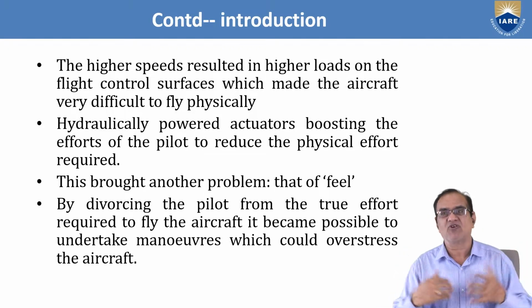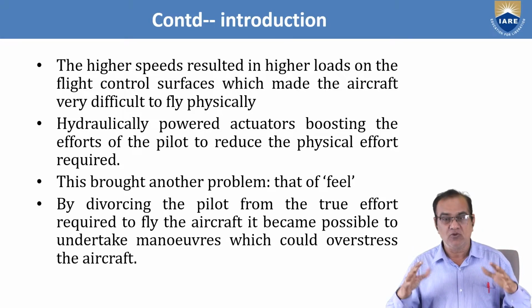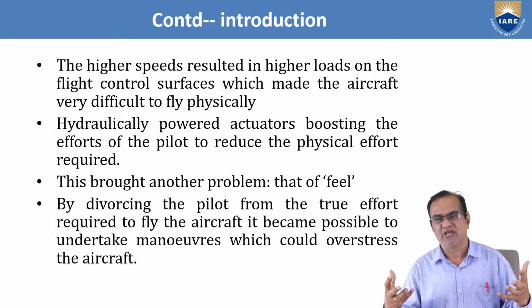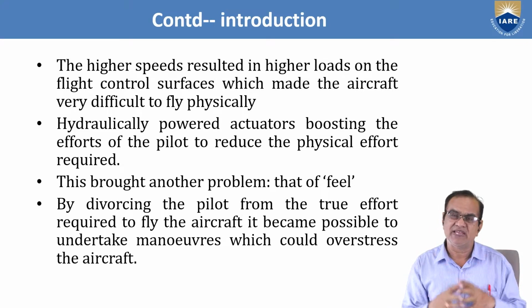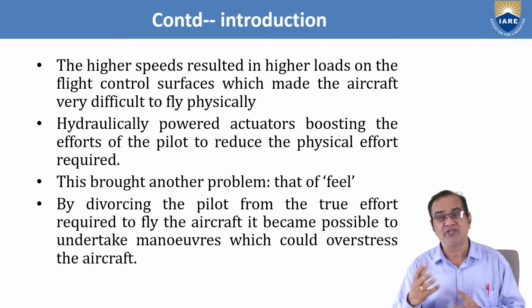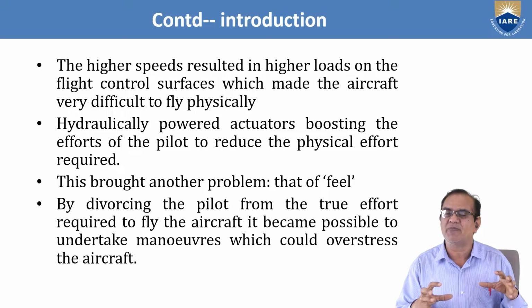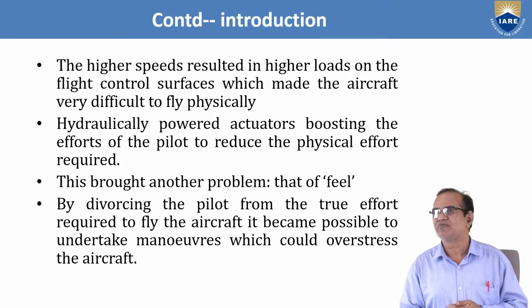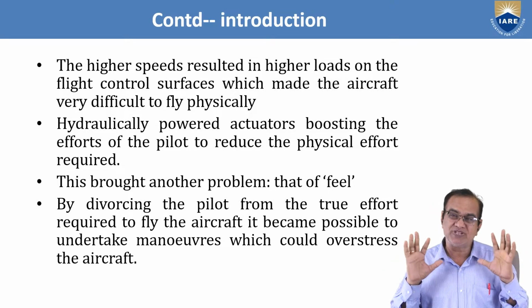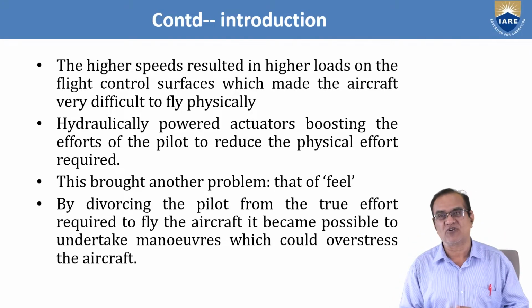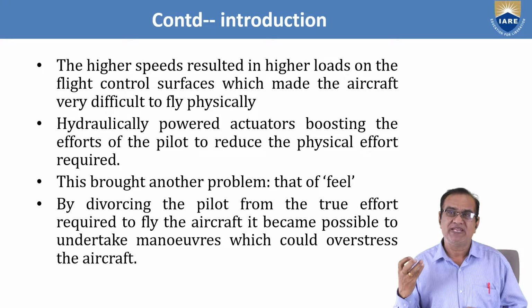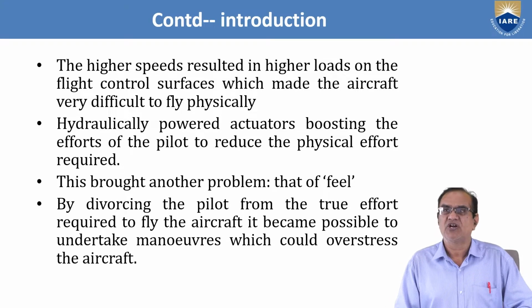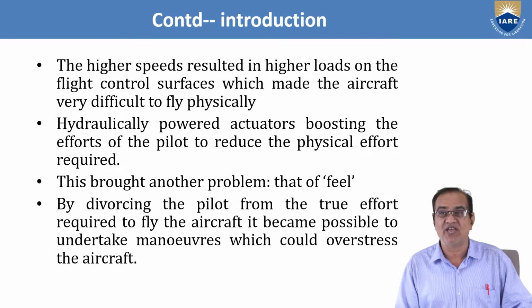Like if you are driving your car or your bike, you can understand the speed, because even if you don't see the meter, you can understand by your experience. But if it is hydraulically operated, the pilot is not able to understand how much effort he is putting on the control. So a feel problem existed. By divorcing the pilot from the true effort required to fly the aircraft, it became possible to undertake maneuvers which could overstress the aircraft.